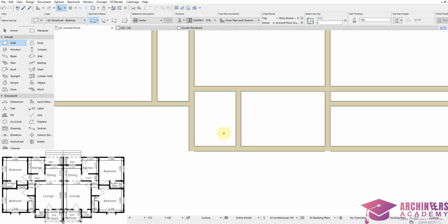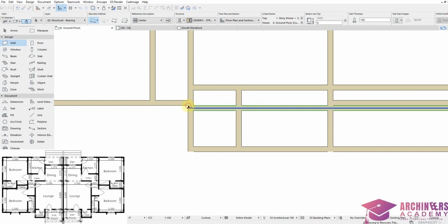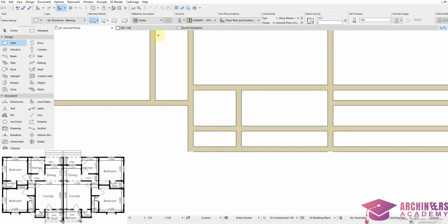I think the width should be around 1000. Control Shift T. How to easily get the width is Control Shift D. You stop it here. Then you add a window thickness of 600. So that is it. So the width is 1050 mm. So I'm gonna trim this off.